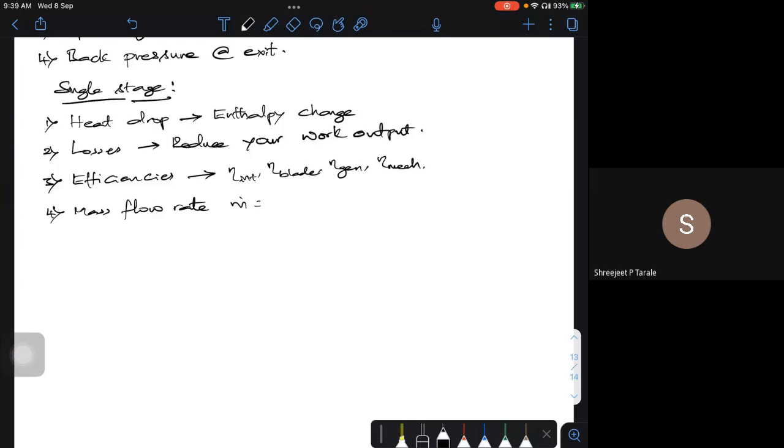So it depends on, maybe, P is equal to omega QH, hope that particular formula. So you have a delta H isentropic into all the efficiencies. Let me put it as overall efficiency, which is maybe the product of internal efficiency, generator efficiency, mechanical efficiency, or maybe your fluid blade efficiency, or all the efficiencies. Once you know this, now your steam velocity with which it is entering your nozzle. So that is also very important.